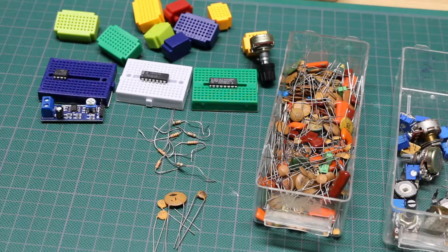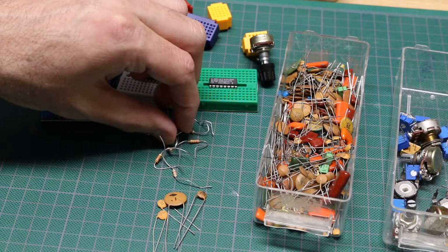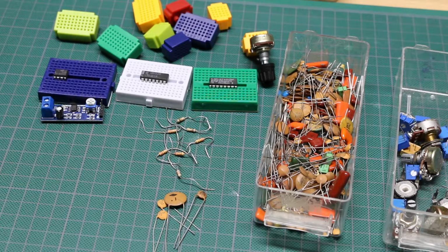I'm going to try using a single supply instead of a split supply for the op-amp. So from a single 9-volt battery, I will connect plus and minus across the op-amp power, but then I need to use 2 resistors of the same value to shift the non-inverting terminal up halfway, 4.5 volts, so that the input signal can swing around that. And then I don't need a dual supply plus and minus 9.